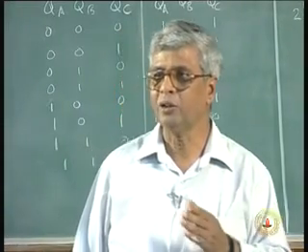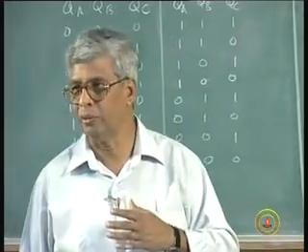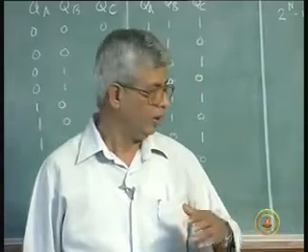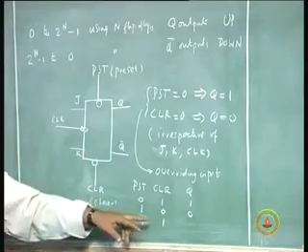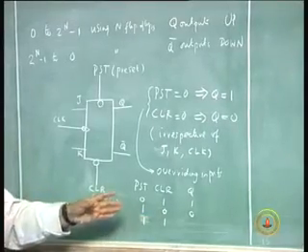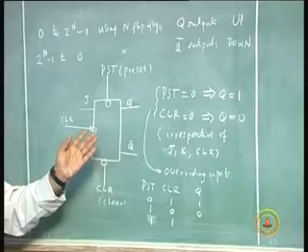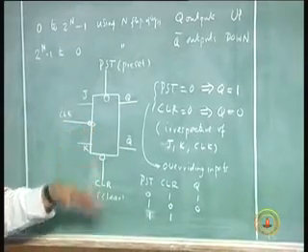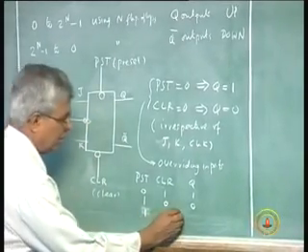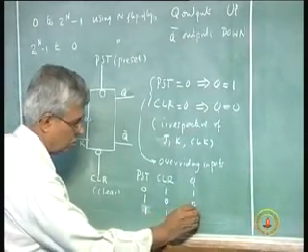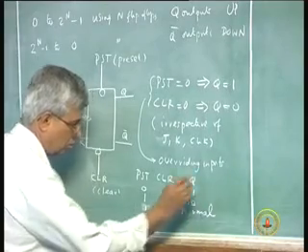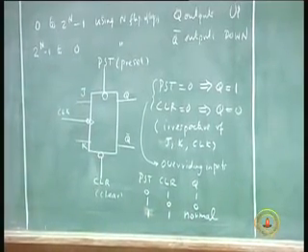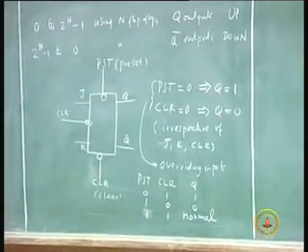At the clock cycle it goes past high or low, all that will be determined. Only when preset and clear are both made 1, they will have no influence on the normal functioning of the flip-flop. So the flip-flop acts normally, as defined by the inputs and the clock.